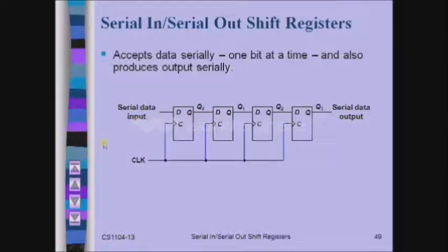Okay, now let us take an example here, assuming that our data input is 1100. Okay, 1100, therefore 1 is the MSB and 0 is the LSB. So initially I am giving the input from the MSB. Okay, so here the input is 1, and during the first rising edge of this clock pulse, all the flip-flops will be processing their inputs. Now the inputs for the remaining flip-flops are zeros, whereas the first flip-flop's input is 1. Therefore this input is processed and it would produce the output as 1. Okay, here Q0 is 1, Q1 is 0, Q2 is 0 and Q3 is 0.